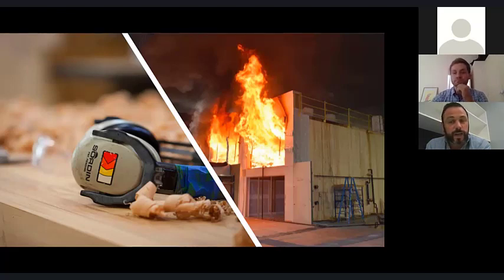A lot of hotels tend to have higher acoustic requirements depending on who you're dealing with and who the user will be. But in essence, the hotel compartment, especially when you're dealing with mass timber, really helps manage that spread, running with really solid, tightly fitted walls either side and a floor. If a fire occurs in that compartment, it's very, very difficult for it to transfer around.